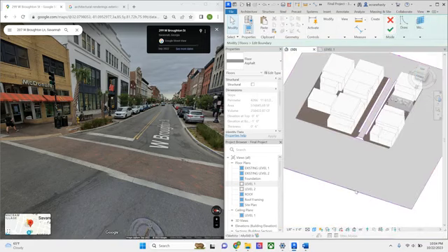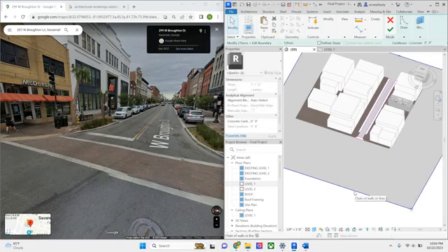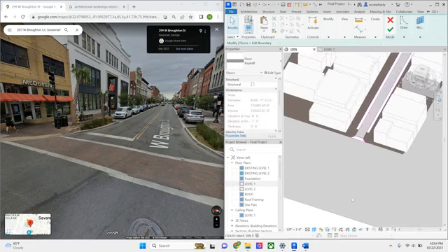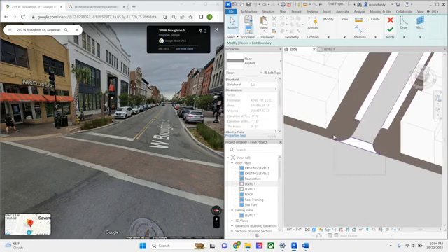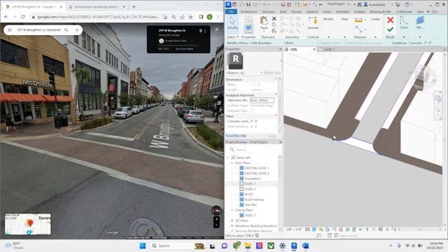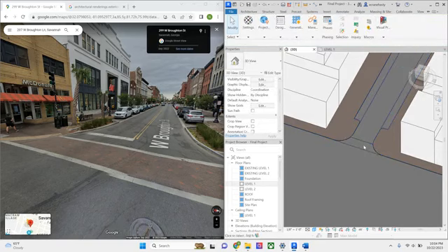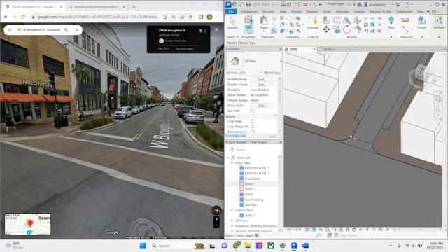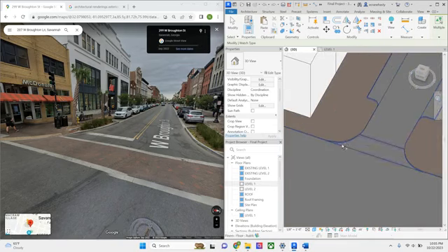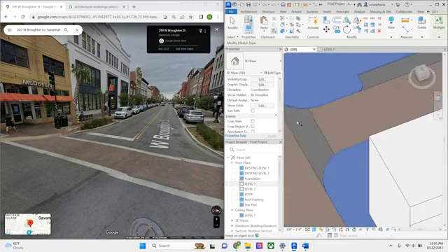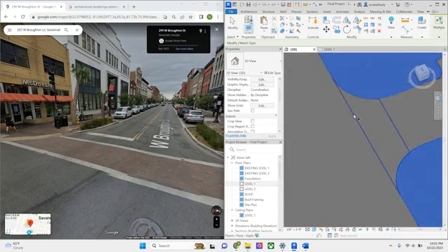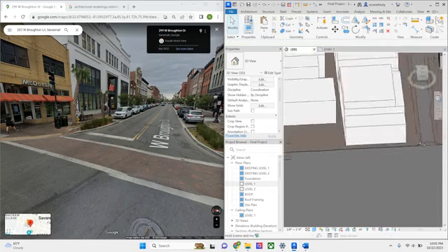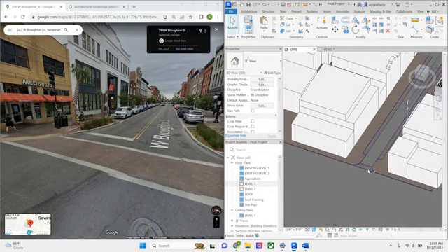I'm going to edit this boundary. I'm going to delete this outer box that's making the holes here. And now that I've deleted the outer box, these guys are going to create the solid, instead of creating a void, they're going to create the solid piece. So when I hit the check mark, those are now the solid pieces, and I can make them the same material. Man, I'm selecting the wrong one. There, I can make those the same material. So just a quick shortcut.